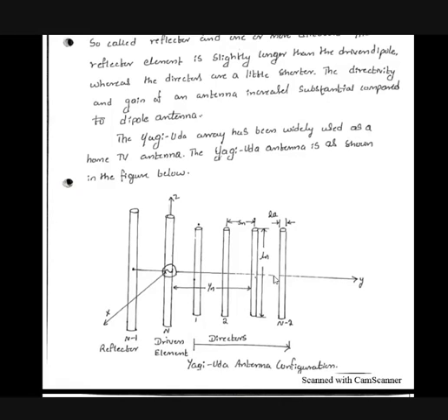Okay, so it is a combination of one driven element, one reflector element, and, as the application requires, that many directors we can add here, right? So this is the Yagi-Uda structure. You can see it here usually.